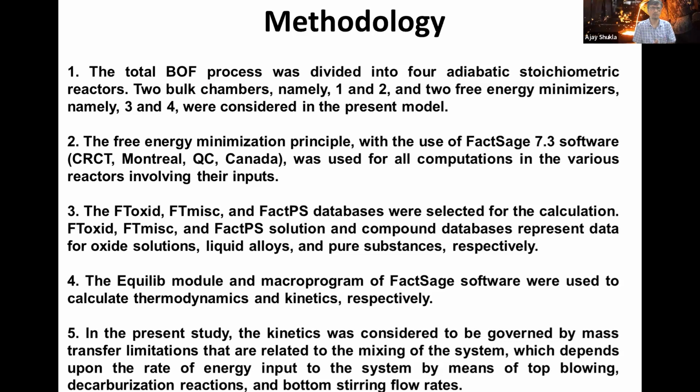So the total BOF process was divided into a number of adiabatic stoichiometric reactors, 2 bulk chambers, and 2 free energy minimizers. And in all these cases, we have used FactSage software, and computations were done in a repetitive manner. So FTOxid, FTmisc, FTPS, all these databases were selected for calculations, and the equilibrium module and macro program was developed. In the present study, the kinetics was considered to be governed by mass transfer limitations,